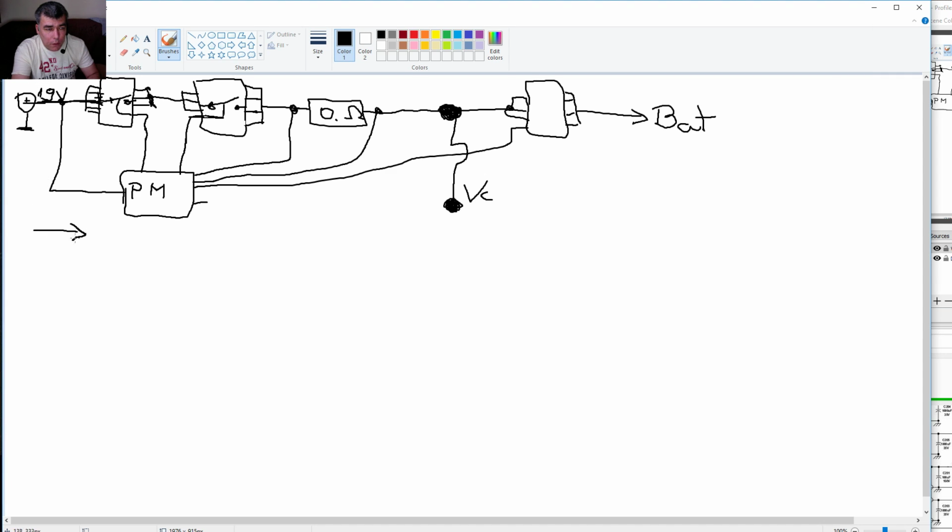That's the power flow, yeah. That's the power flow coming here, and it is also charging my battery. And this chip is also controlling the charging current on the battery. This is when the charger is plugged in, yeah? You see these arrows, yeah? When the charger is plugged in, it is also charging the battery.